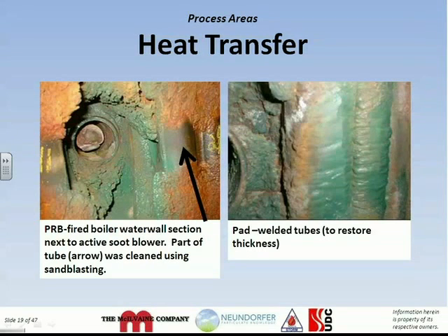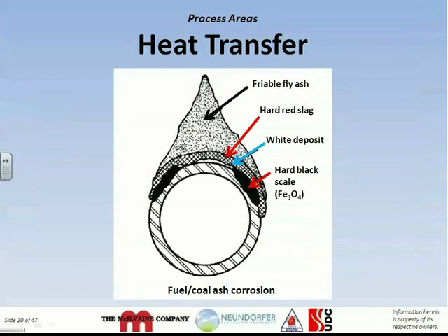What is typically left out of the equation is a joint effort involving the combustion performance and environmental people. As mentioned by Dick previously, if we get the combustion right, then the formation of slag and ash is reduced, and subsequently the removal of slag is reduced, and ultimately multiple benefits can be achieved. Our responsibility is to supply meaningful information in the form of quantity and specific locations of ash and slag to the combustion folks so they might better apply solutions to reduce the slag problem overall. This reduction of slag not only helps the overall tube life and reduction of forced outages caused by its removal, but also helps the distribution of heat more evenly across all pressure parts.